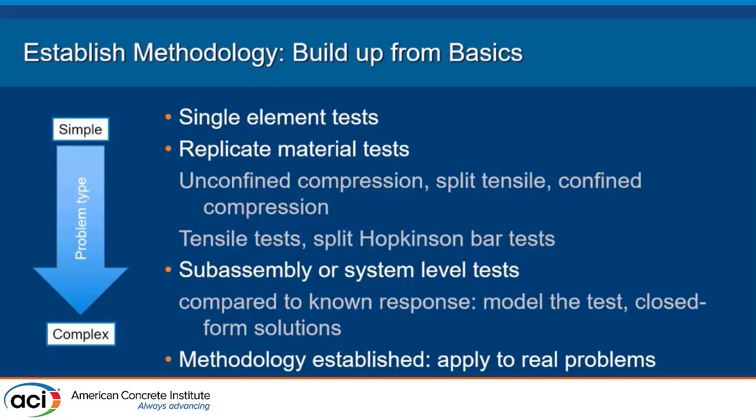If at the start I don't know how a material model behaves, I've never used it before, or I don't know how that finite element works, I'll do single element tests and I'll stress it in ways that I intend to stress it in my application. So I know from one element how it's going to react. And then replicating or calibrating material response is super critical.